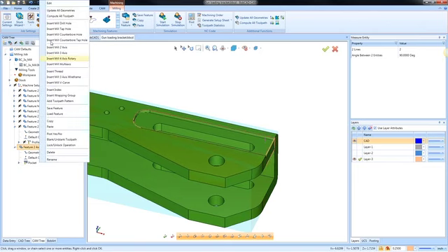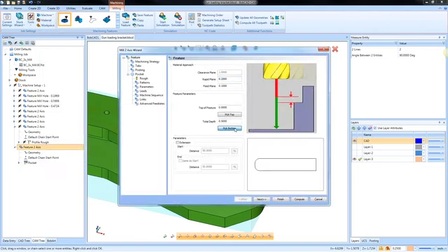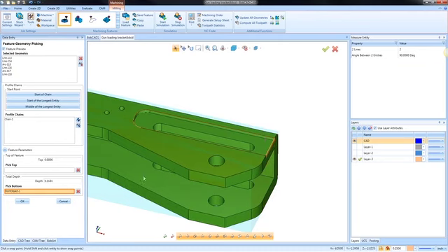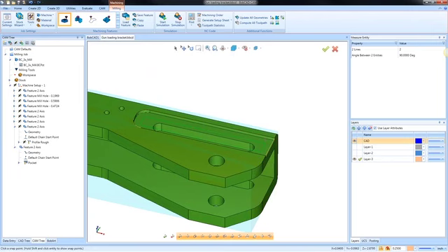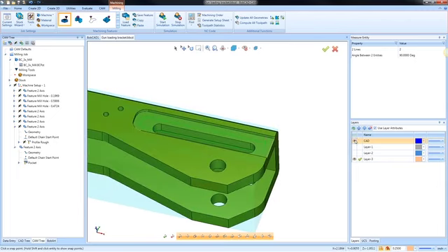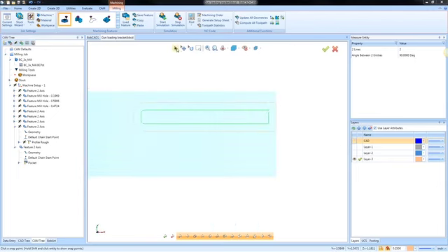All right, so a couple of things. Let me edit this feature. I'm going to do pick bottom because it went to the default depth. So I'll say pick bottom. Okay. I'll recompute here. You can see the tool path that's on there. All right. We actually want the tool to go outside of this edge here. So how do we do that? We're going to go to selection mode. Okay. And we're going to select this line here. All right. And then once we have it selected, we're going to right click, modify attributes, line style, and then we're going to turn it to a dotted line.